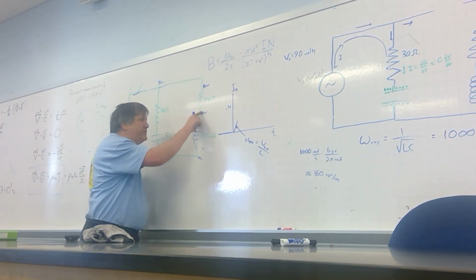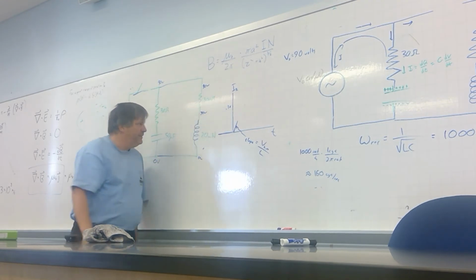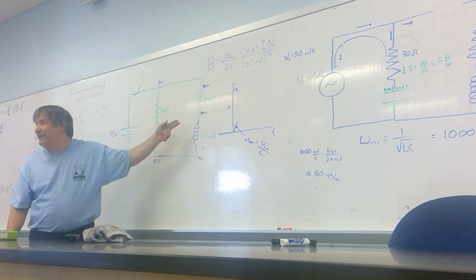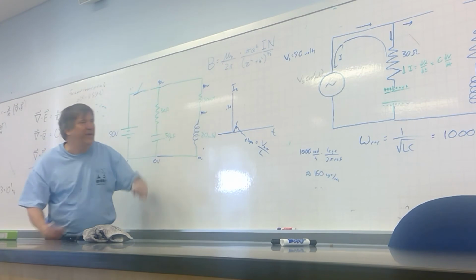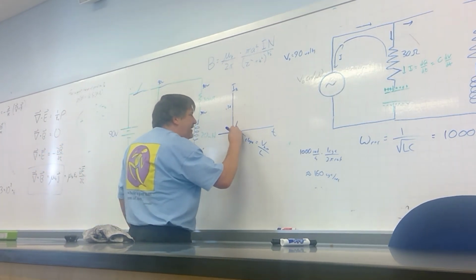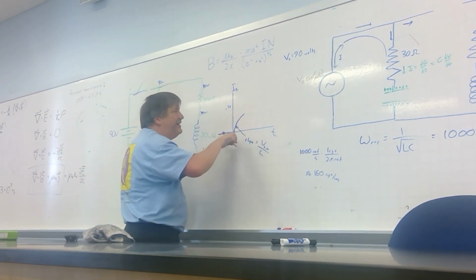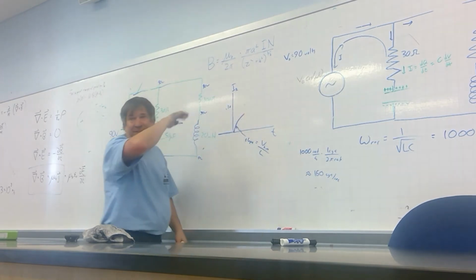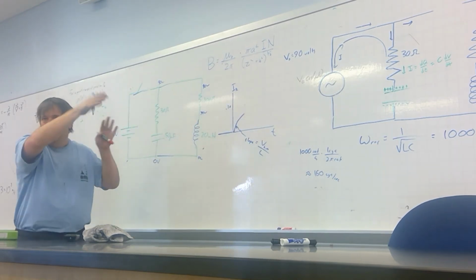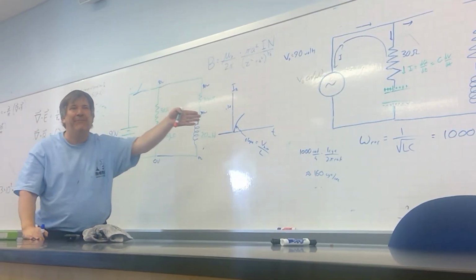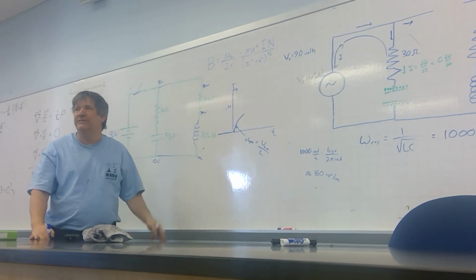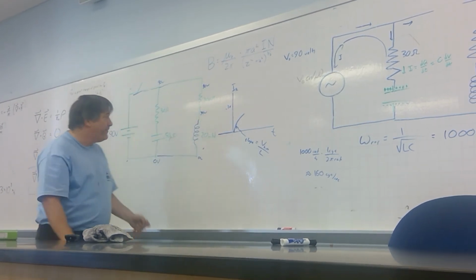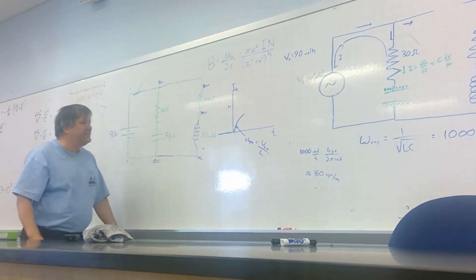And if, say, that voltage drop has hit 20 volts, well, now I've only got 70 volts left to apply to the inductor. So the rate of change of the current through the inductor begins to slow down. You see what we're getting to. It's eventually going to level off. It's going to give me one of those 1 minus e to the blah, blah, blah charging curves.